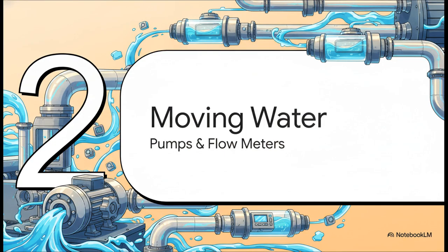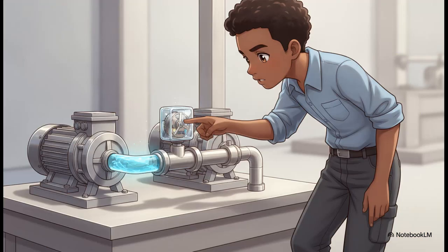Moving on to step 2, let's talk about getting that water moving with our pumps and flow meters. This right here is where the optimization of the mini ETP really shines. To move 5,000 liters of water a day, you don't need a giant industrial pump. You just need a feed or raw water pump, submersible or centrifugal, either works, with a capacity of exactly 1 cubic meter per hour. Since 5,000 liters is just 5 cubic meters, you're only pumping for a few hours a day to move your entire volume.